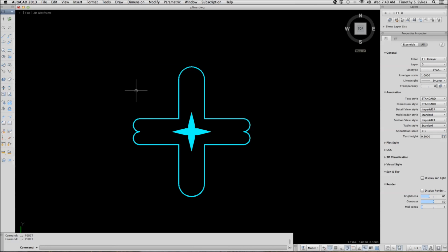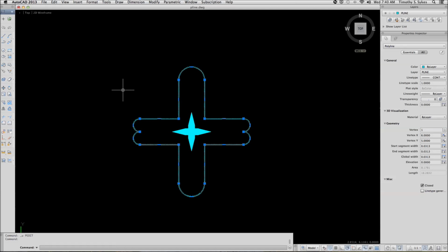And we'll move on to exercise 12.2d, working with polyline editing grips. If you select a polyline without double-clicking, AutoCAD will present its grips. You have two types of grips. You have a primary grip that appears at the vertices. If you hover over that grip, AutoCAD will present a menu allowing you to stretch, add, or remove a vertex. If, however, you hover over the secondary grips, you can stretch, add vertex, or convert to arc.